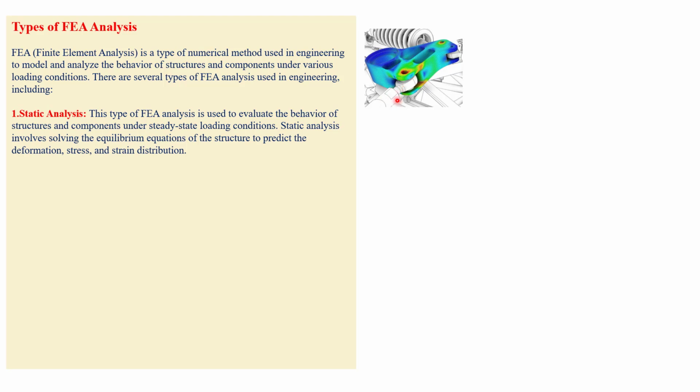We have the different loading conditions and the boundary conditions. With respect to the neighboring components loading on this particular component, you can see the stress hotspots, you can even extract the factor of safety and the displacement, how it is behaving, and depending upon that you can predict what needs to be done.